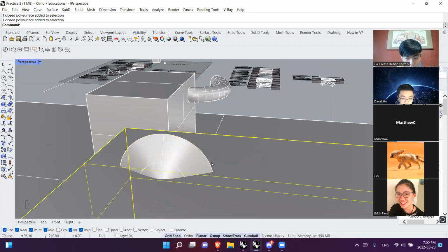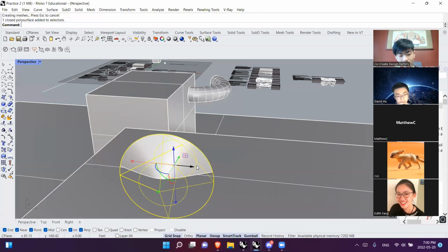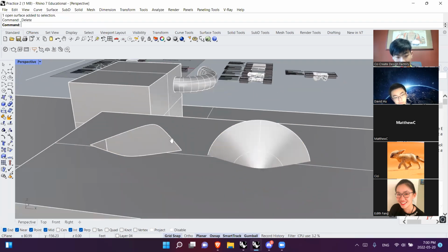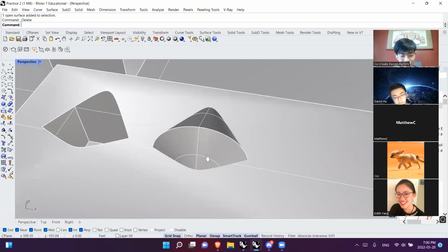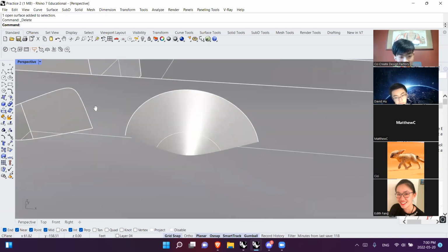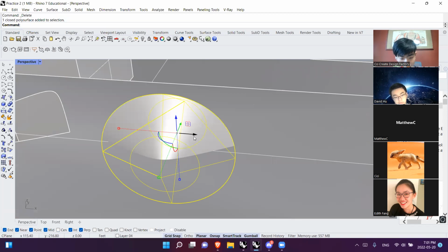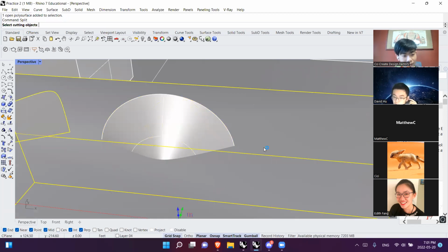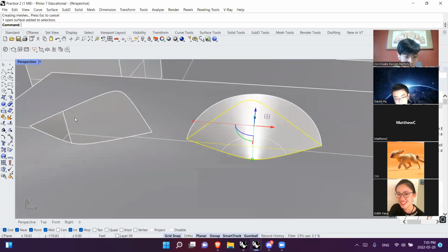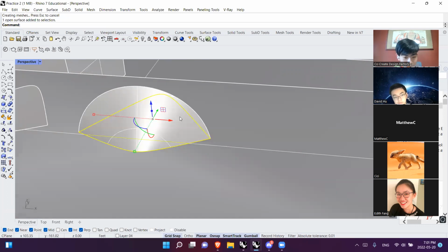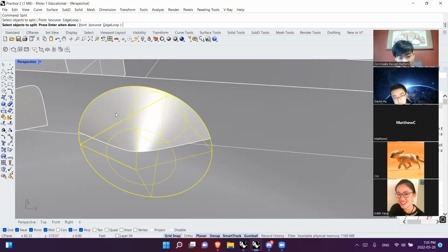So there's one way, which is split, cutting object is that, and let's move it over here. You just delete the surface, right? So you can see inside. So it's like cutting a hole. But there's also another way that if you want this to be filled in, you can do split again. Cutting object is that. And now you have your surfaces here that we deleted in our first example, right? But we can split, okay, this is going to sound a little confusing, we can split this shape with the shape here.